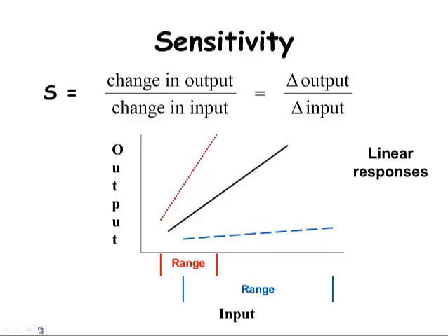When purchasing a sensor or transducer, it is important to know what input range you plan to use the transducer to measure over and what kind of sensitivity you need. It is usually difficult to have both a large input range and a large sensitivity.